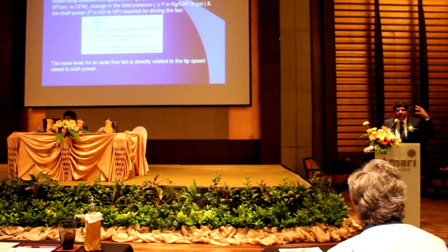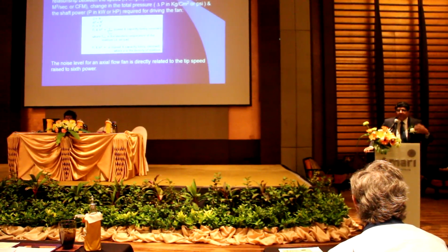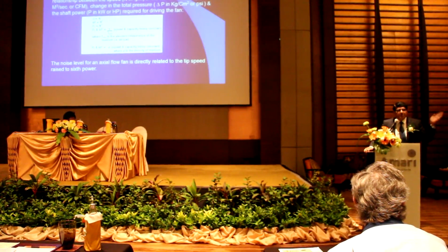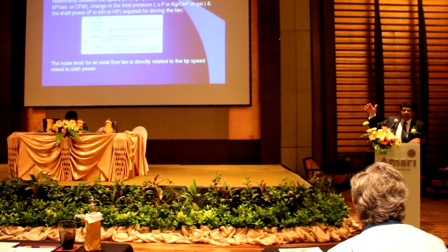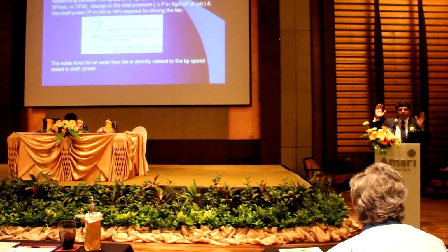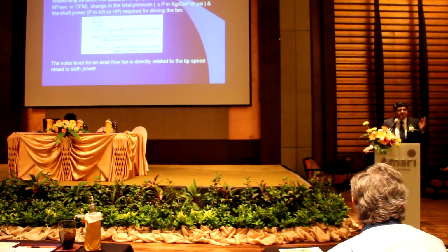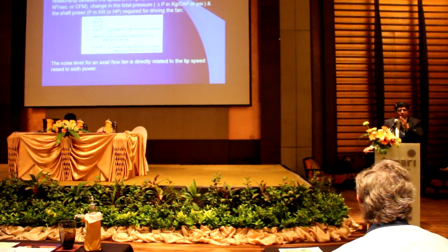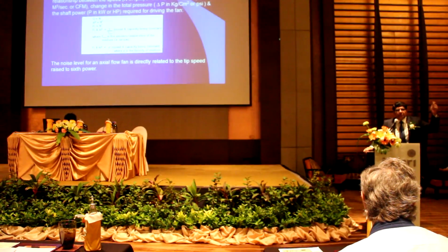Then, although the power consumption goes up, because that's what anybody in the plant would look at, whether your amps have gone up or not, it happens without the knowledge that the blade has already stalled and it's actually recirculating right there, rather than sucking air through your system. So it's not always that you just keep a close watch on the motor power and go on increasing.